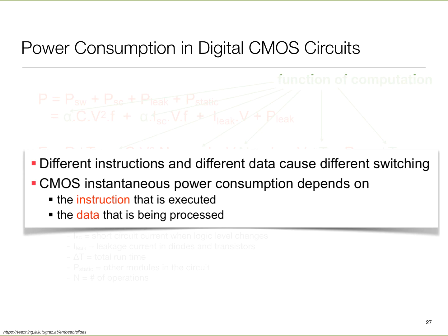Of course, if your processor is running at a megahertz and you are sampling at kilohertz, then it's all going to be sort of low pass filtered out. So you need to have a high enough sampling rate, and you need to have a sufficient number of bits to be able to see the differences that are happening. But if you can, then it's a reasonable hypothesis that my power trace, and also the energy consumption over some window, are going to reflect what has happened.